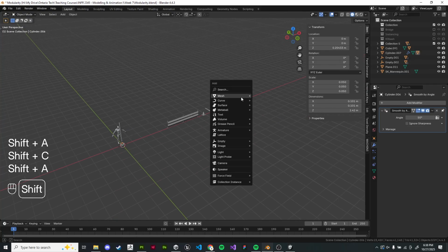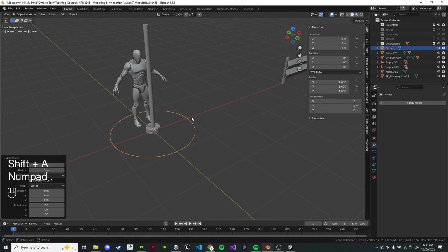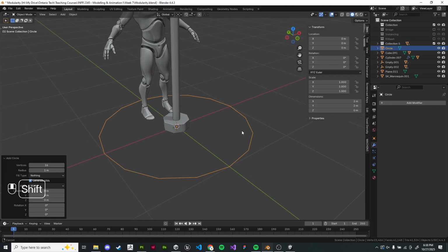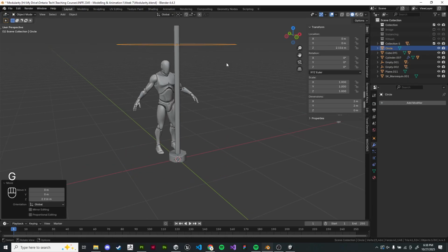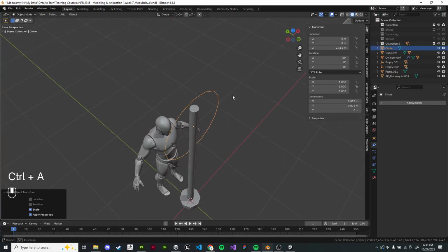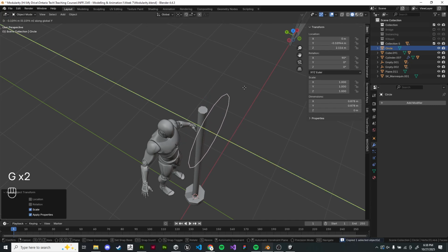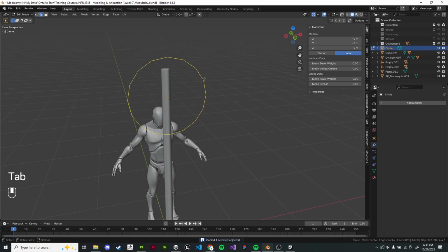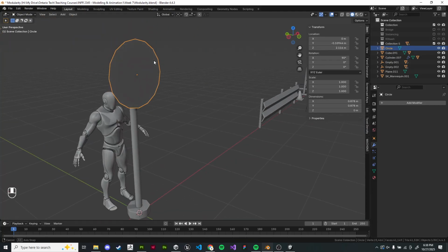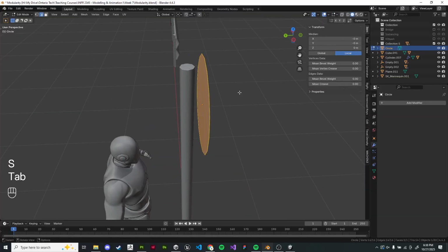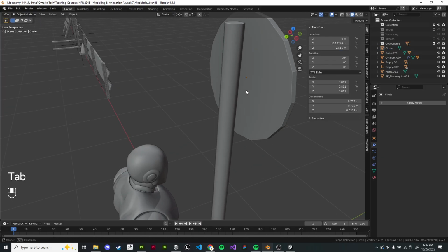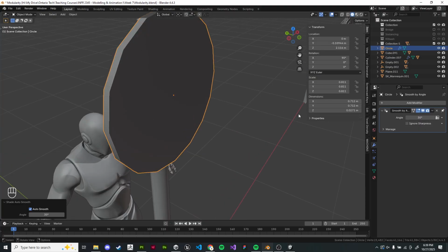and we'll add a new circle. And I'm going to keep this one at 16 vertices to act as a round sign. So now I'm just making sure to move it into place. Press F to give our circle some actual circleness. And then E to extrude it out a bit and give it some thickness. Same thing with the shading smooth.